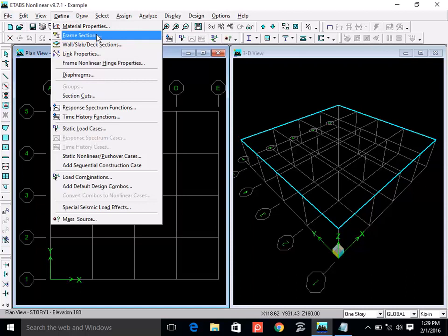Now the question is that at the beginning, when you are designing the structure, you are not sure about the sizes of beams and columns, which means you need to do some approximation, or use some guidelines which tell you tentative sizes. Most of the time, the sizes we begin with are based on deflection criteria.